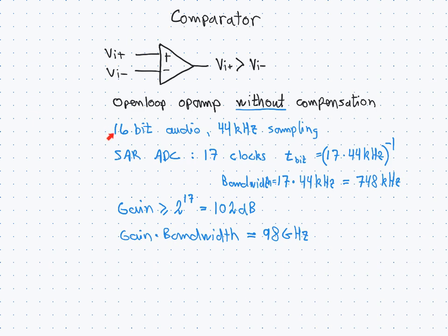This is an extremely high frequency, certainly for something that is processing just a fairly conventional 16-bit audio signal. And this is really highlighting why we can't just use an op-amp as a comparator, because in most but the really slow cases it would simply not have the speed. It might have the gain, but it will not have both the gain and the speed.